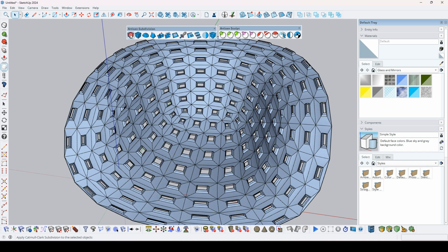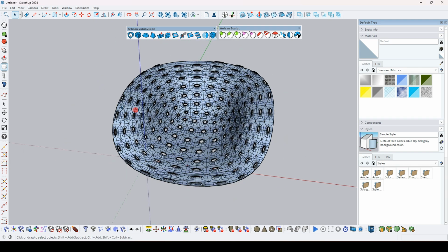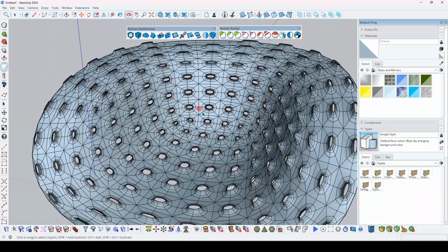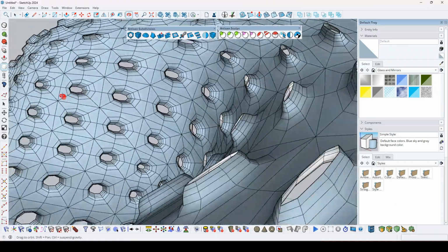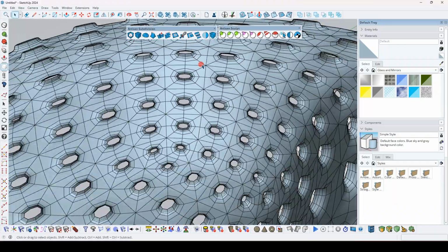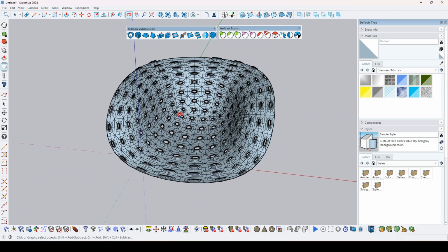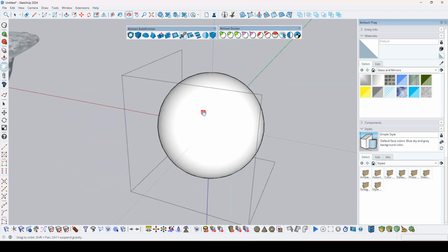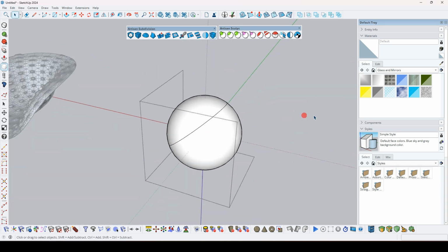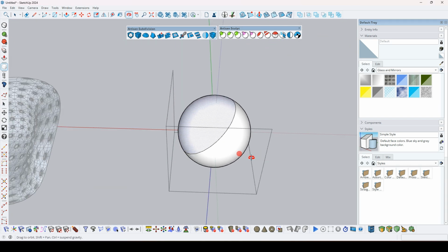This time I am using this option, subdivide and smooth. So now you can see that your models are looking more complex just using a few tools of this artisan tool. Okay, you have to use this knife subdivision option. So just select, drag, press alt, and then again click to cut, just like that.